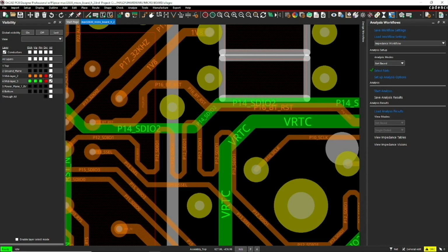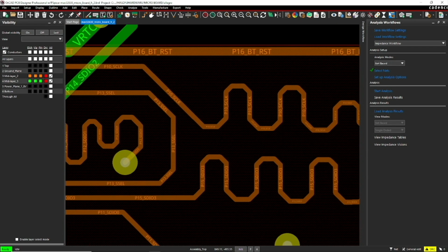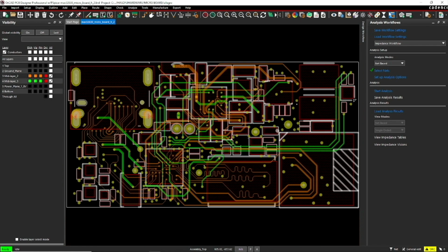You'll end up seeing squiggly lines to achieve this, and that's what the engineer did here. They wanted the time delays to match a specific arrival time, so to speak, for the main microcontroller. How do you determine the required time delay? There are two ways. You can calculate them yourself using various signal integrity methods and software, or you can check the manufacturer datasheets and design guides. I would recommend using the datasheet and design guides. It's much faster and most likely more accurate. In fact, this faster method is common practice because it just saves time and is likely more accurate anyway, even for senior PCB designers.